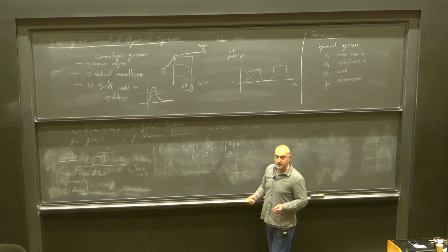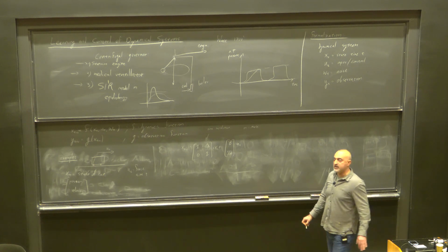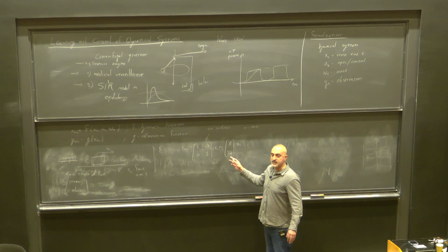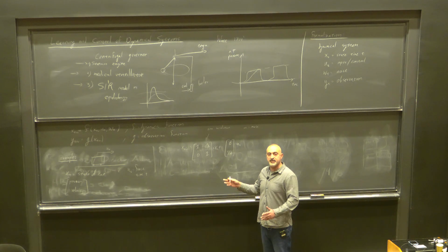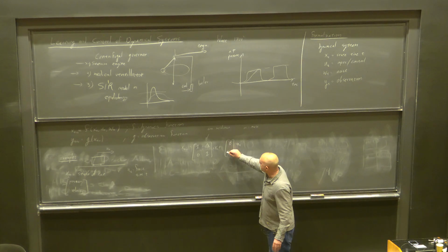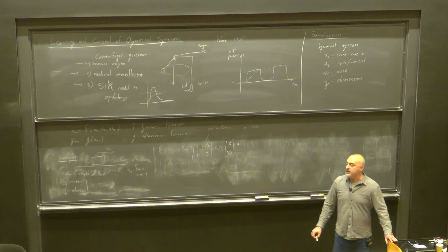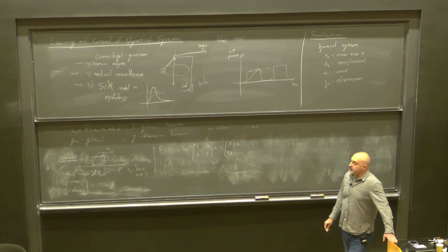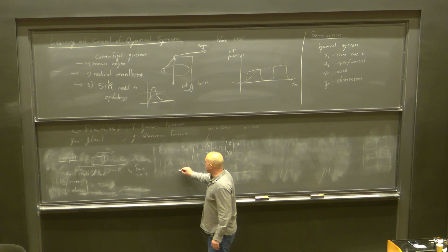And if we measure the force in Newtons, then F equals ma means that the acceleration is force divided by mass, and I add to the velocity at time t the acceleration, to get the velocity at time t plus 1. Yeah, delta divided by mass. Correct. So this is a dynamical system. It's usually called the double integrator.